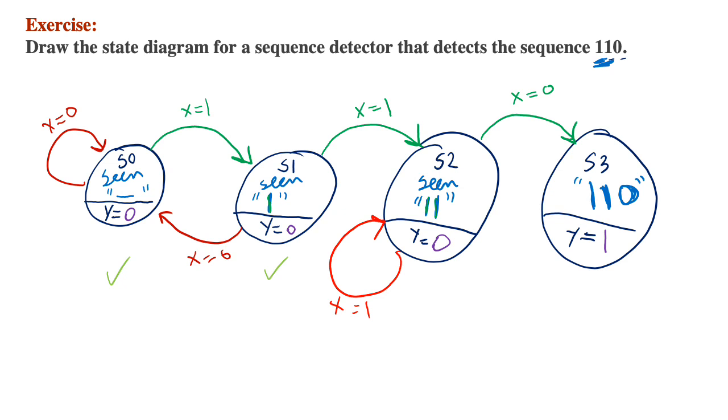Now we'll examine the last state. I'll check what will happen for both cases. The first case is when I receive a 0. So let's write whatever is inside the quotation mark. It's simply 1 1 0, and then write the next possible input, which is 0. And then check only the last 3 bits, because the length of the sequence is actually 3 bits. So I will cross this old bit. I'll be left with 1 0 0.